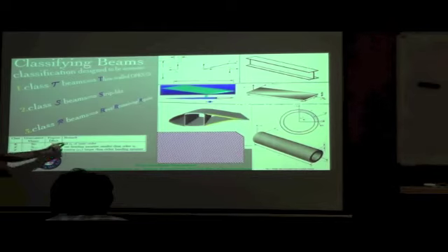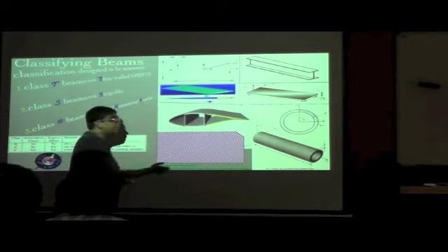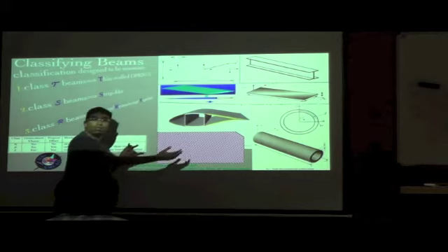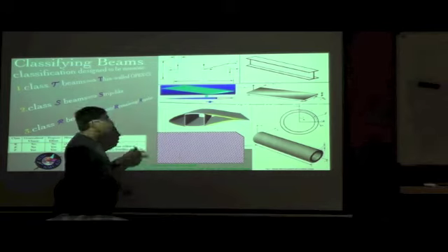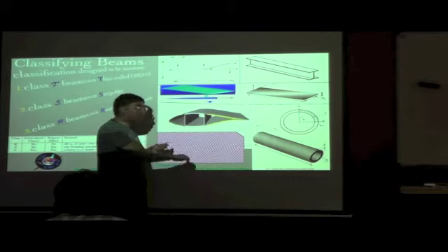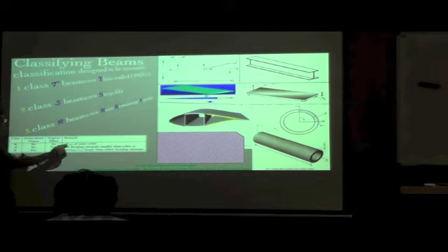And the reason is all the kappa of such beams, or class R beams, are of the same order of magnitude. So in other words, for a bending moment like this and a bending moment like this, the stiffnesses, of course, are going to be different. EI2 and EI3 are numerically different, but they are not an order of magnitude different from each other. They are of the same order of magnitude. Similarly, the torsional stiffness is also of the same order of magnitude, and therefore the curvatures associated with it, which are kappa 1, kappa 2 and kappa 3, are all of the same order of magnitude, and therefore neither of these effects becomes important.